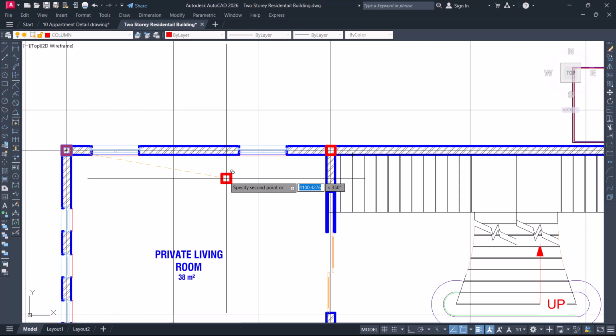And when a beam becomes more than 6 meters, the beam deflection becomes heavy, because how a beam deflects is based on the length. The more the length of the beam, the more the beam deflection. So it has been seen from experience that once your beam span length is less than or equal to 6 meters, you have lesser deflection on that beam.